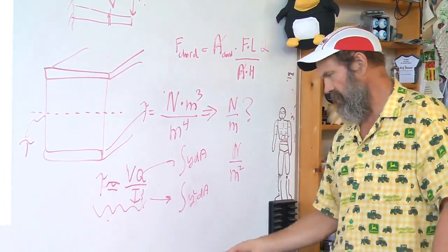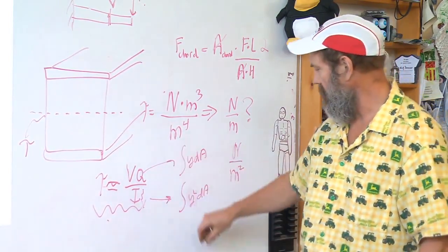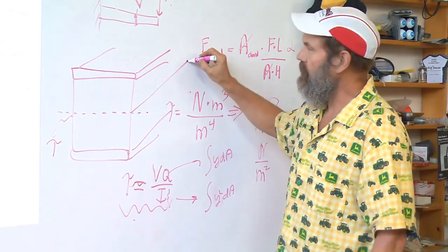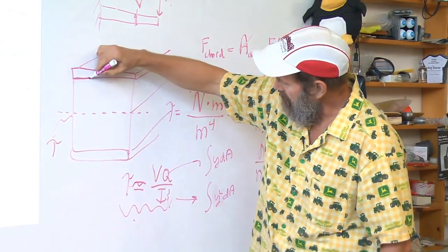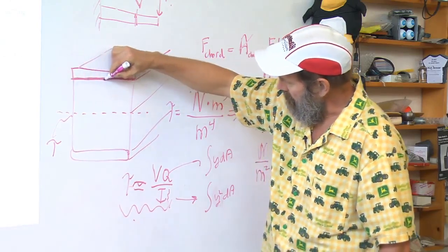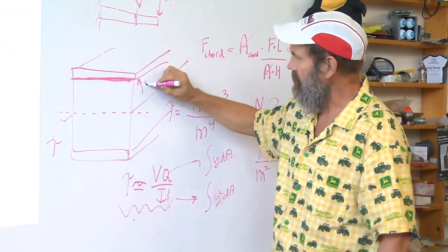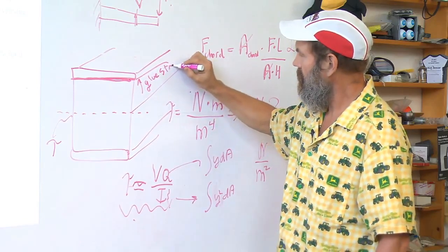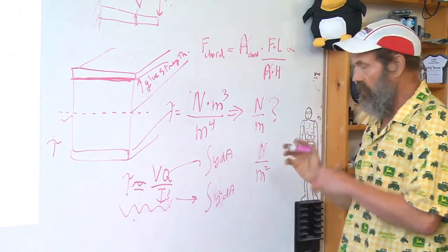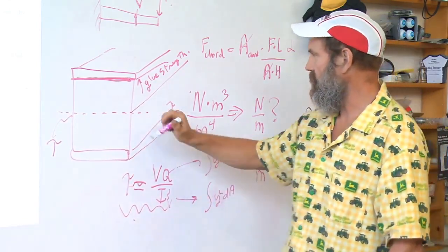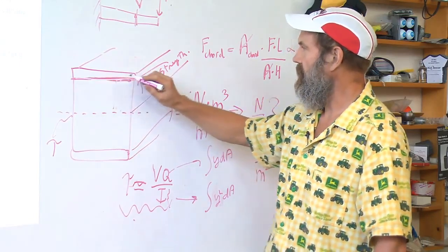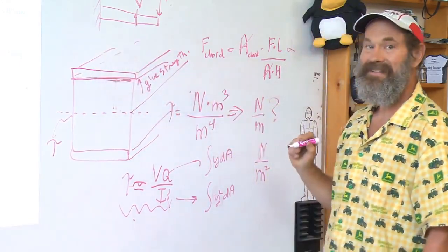The key thing is that you can calculate what is happening in this plane. You can also calculate the shear at this level to determine the glue strength. So this is starting to give you a hint of how do I define Q? Is it the first moment of this area, of this area? Okay, go look it up.